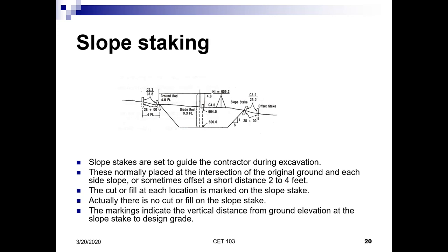Remember, the section is a part that's either left or right of the center line alignment. That is usually determined by the stationing and the way the stationing increases. One would always look toward the way the alignment would be increasing and then look left or right of the center line at that point.